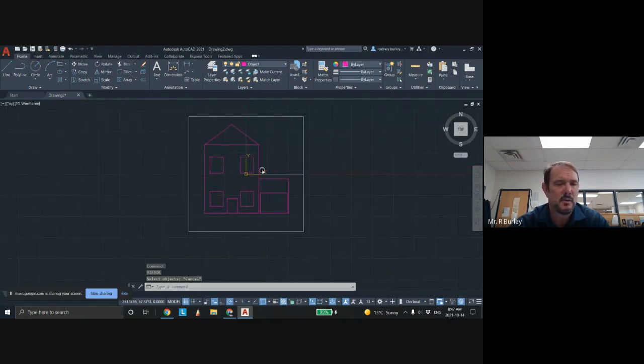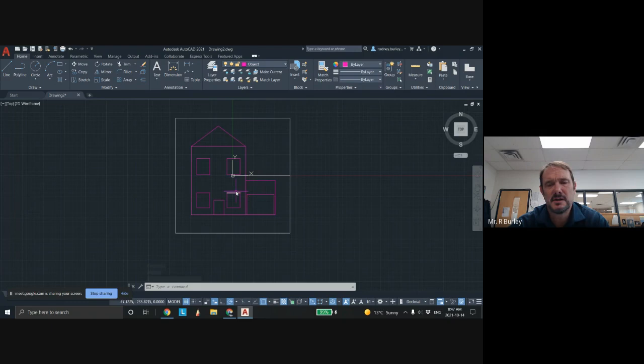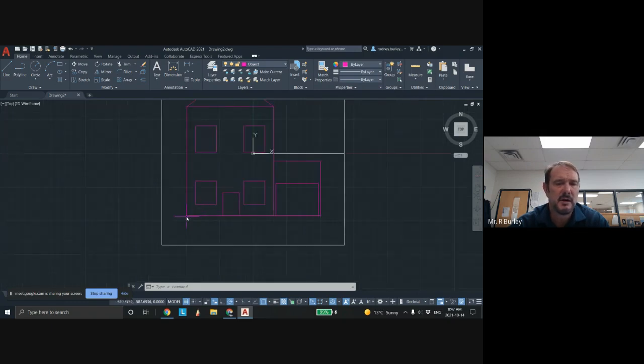Now again, like I said, what we're going to be using this information for is, let's say we wanted to draw this wall over here. We come over here, ID point, and select that point right there. And you can see right there on the bottom, there's the Cartesian position of it. So it's in quadrant 1, so it's negative, negative, negative 616.0459, negative and 557, and so on. You can copy it and paste it into the other number thing, or you can just walk over and type it in. And so what you do is you would send your robot to that position first, right?